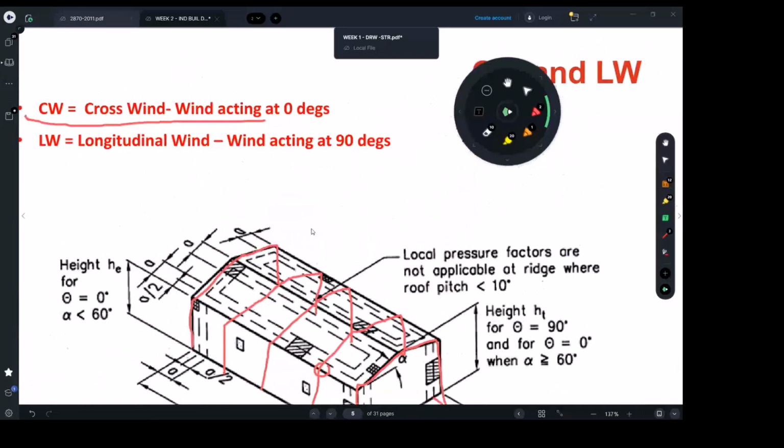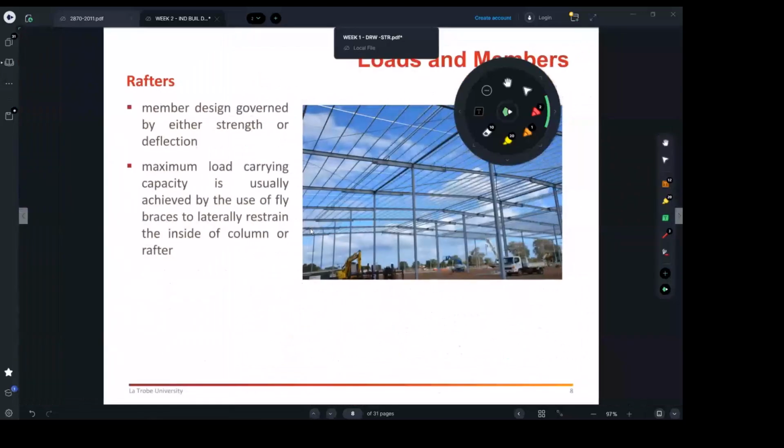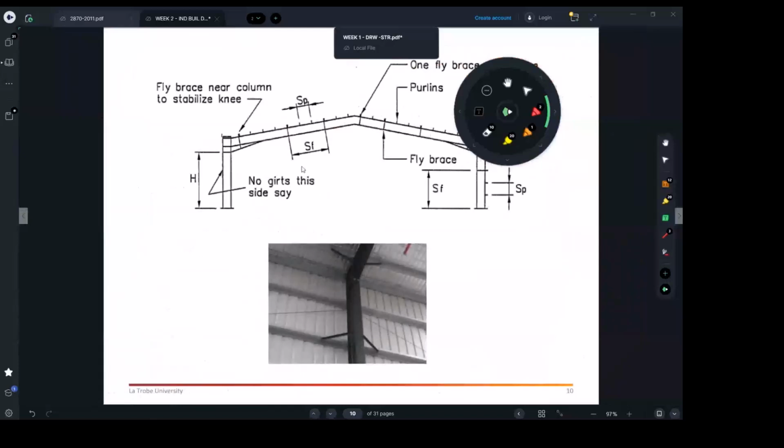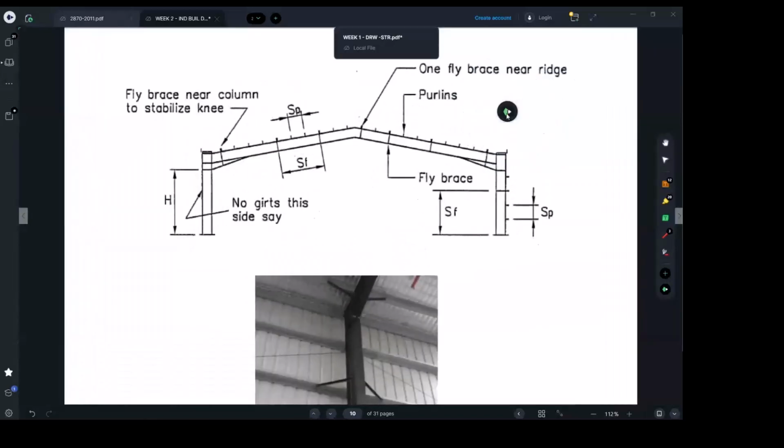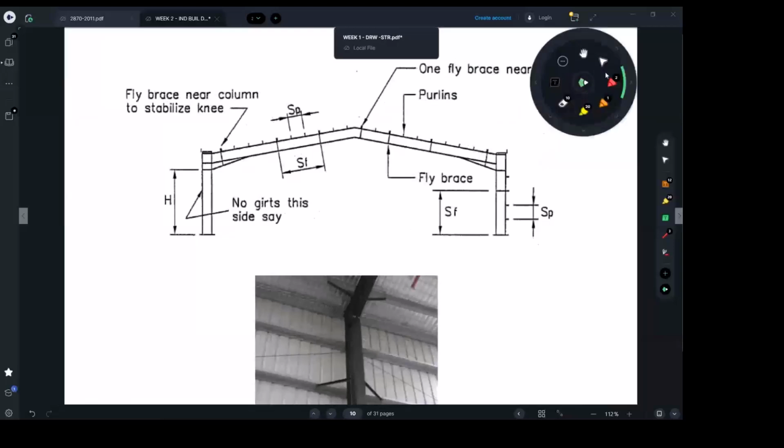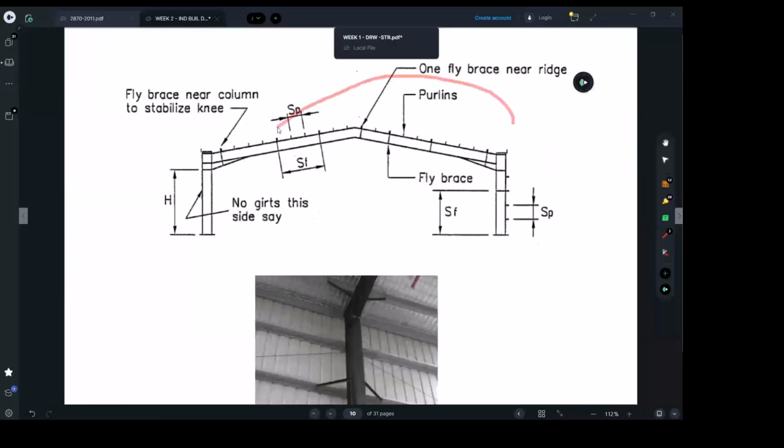Yeah, the portal frame is, hopefully I've got a picture soon. Here we go. This is a better picture. The portal frame sits like this, okay? And they are intentionally done like this in order to portal itself. The word portal means you're bracing yourself. As I said, if you're standing in a tram or a train and you want to brace yourself, you kind of open yourself and stiffen up yourself. So when the forces or reactions come laterally on you, you can stand against them.